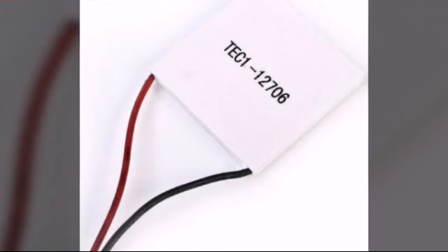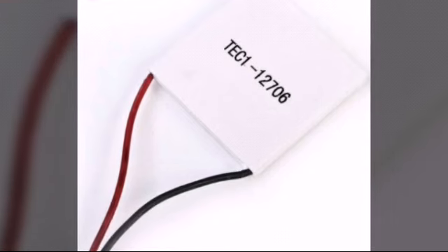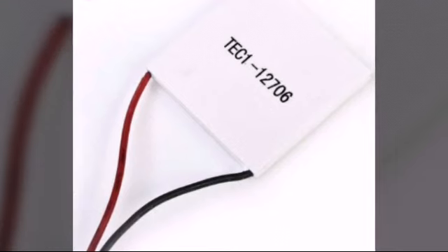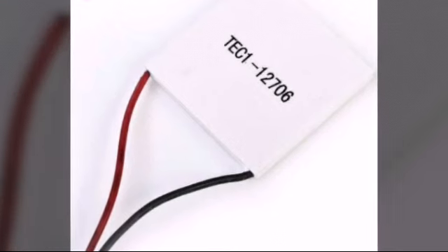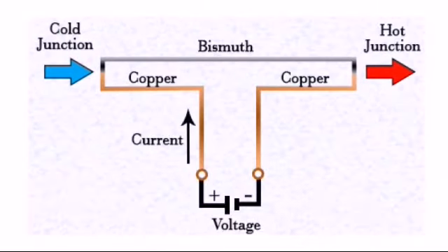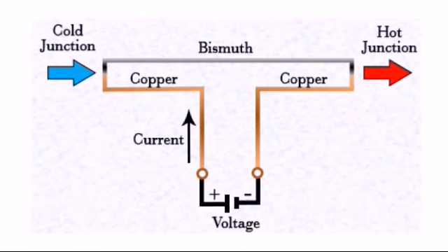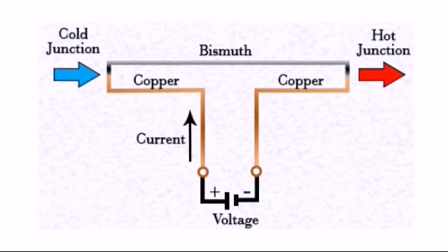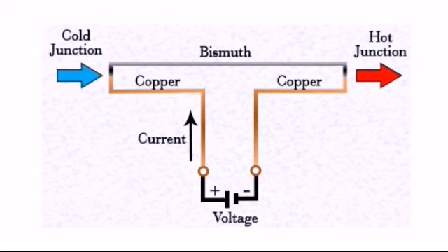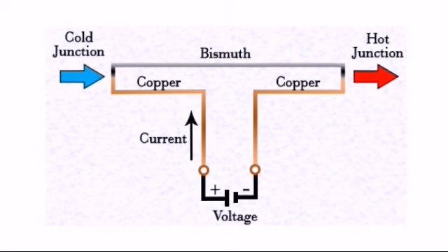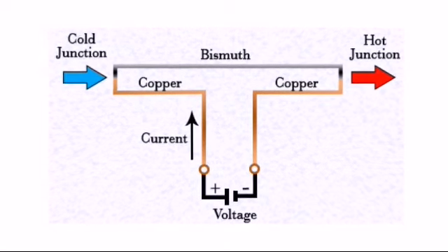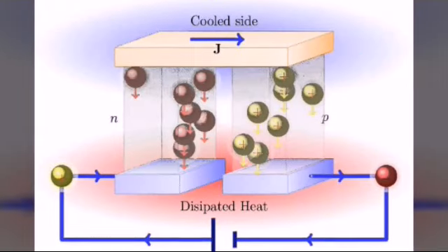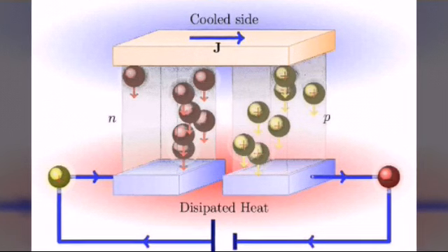This removal can create a temperature difference of up to 70 degrees Celsius. The temperature difference in the module can be up to 70 degrees starting from 10 also. The amount of heat that is removed from one side of the element leads to the maximum efficiency of cooling produced from that element, which is used for the air to condense into water droplets.